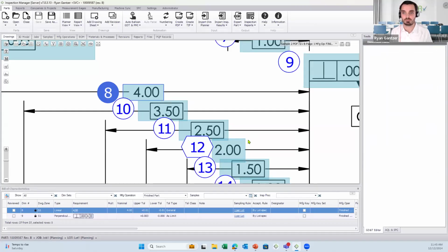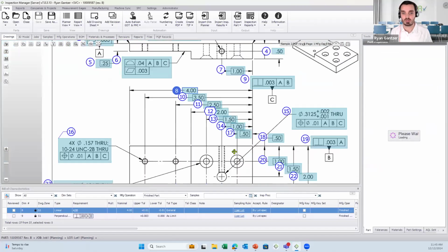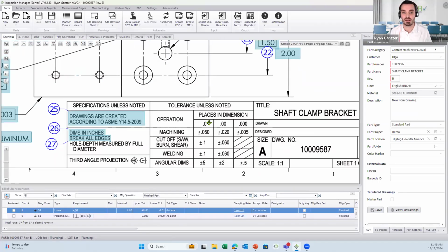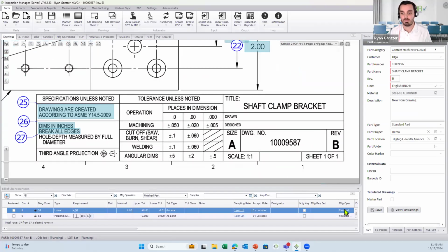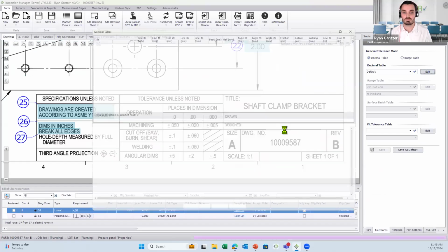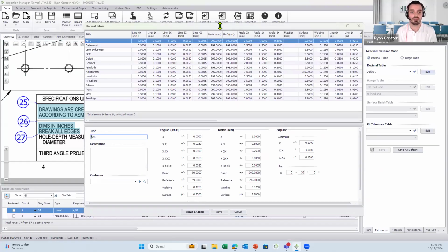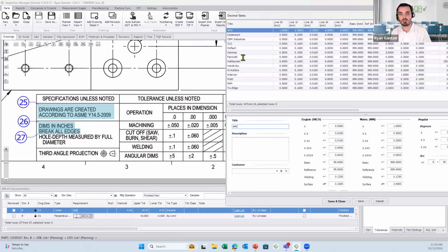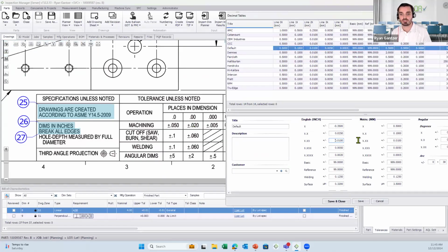To show, because if you recall, we're not looking inside of this tolerance block. But if I go to this tolerances tab down here below, this will give you a peek into where these tolerances are coming from. So that plus or minus 10 thou, right? Based on 2 decimal points in English, we're going to plus or minus 10 thou, again, if the tolerance isn't on the print itself.